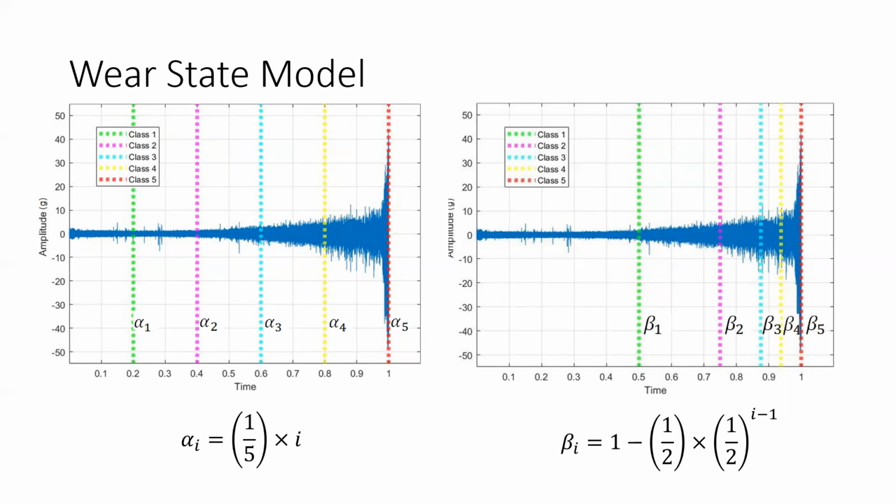Analyzing the vibration signals in the time domain shows that the latter stages of the bearing's lifetime should be given a much greater emphasis, as the signal amplitudes seem to increase at a much faster rate here.